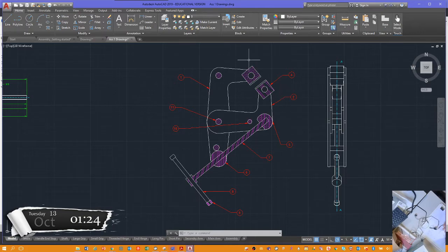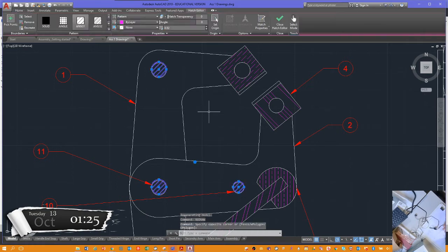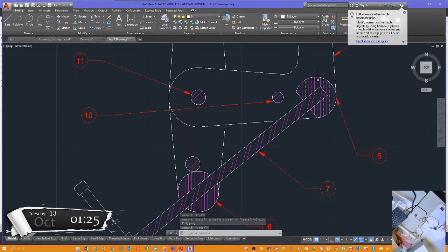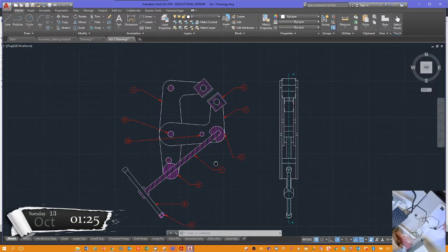So our crosshatching then, you'll notice we've got different styles of crosshatch, and each style of crosshatch shows us it's a different part. All those parts are the same part that we can see. That's a different part to that part, and then these are all different parts that we've cut. I'm not showing the crosshatch on that because it's just a round bar. Technically, I probably should do that crosshatch like we just saw in the 3D view.